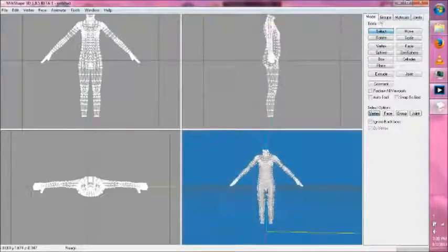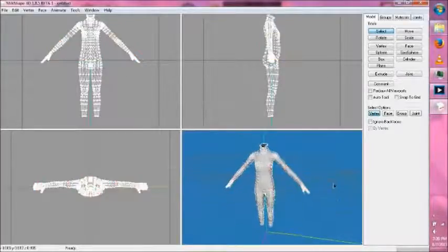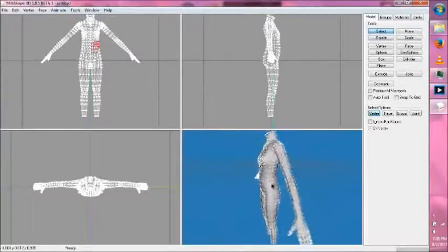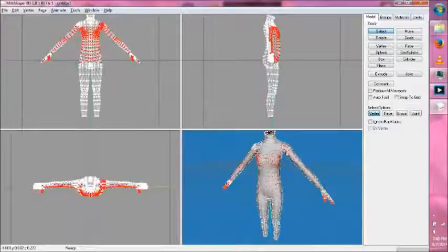Now we're going to move on to your bread and butter, the Model and Groups tab, and Materials as well. For right now, we're going to leave joints alone because they're not really that important if you're just going to do a couple of small edits. Now then, selecting, ta-da, and that's pretty much it. And if you want to select, say in the 3D viewer, you hold Alt and drag, and you can select in the 3D window. And if you want to select more, you hold Shift at the same time, and it follows through in the Alt window as well.